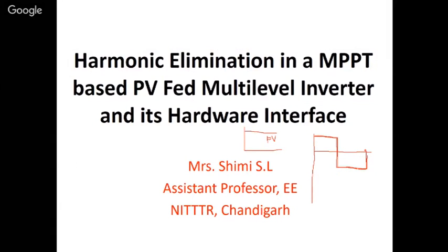Now, this is one type. But whenever you have an AC load, you have to connect this inverter to the AC load. You require a pure sine wave, otherwise your load also will get damaged. So here you require a pure AC. Getting a pure AC is a little difficult. You can have an inductor capacitor circuit like series and parallel inverters.